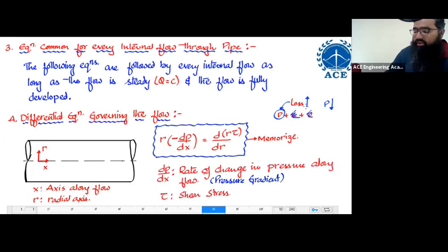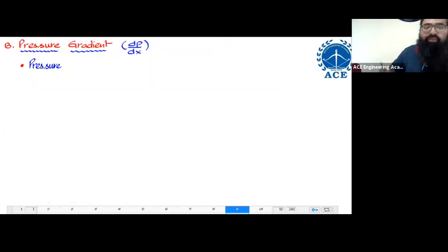Now you see, loss is increasing along the flow. So what will happen to pressure? Decreasing. It is sacrificing. So pressure decreases. Very important word, decreases. How is it decreasing? Remember this thing: since the flow is steady, the decrease in pressure is supposed to be linear. Pressure: first thing, decrease; second thing, how does it decrease? Linearly. Pressure decreases linearly along the flow.